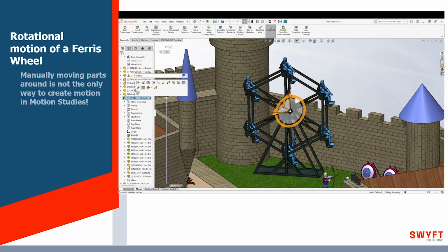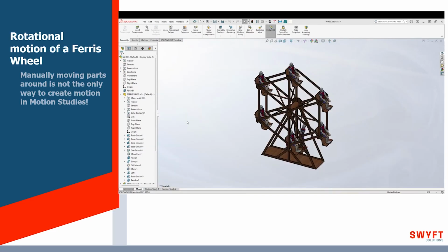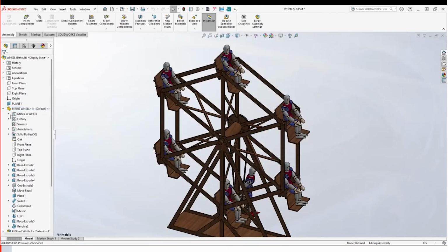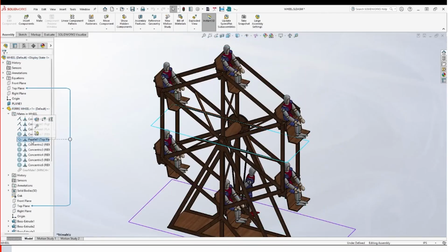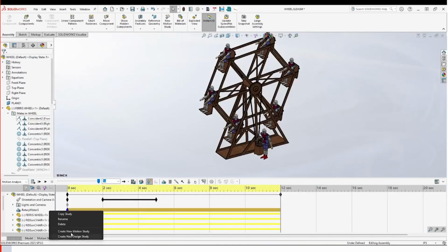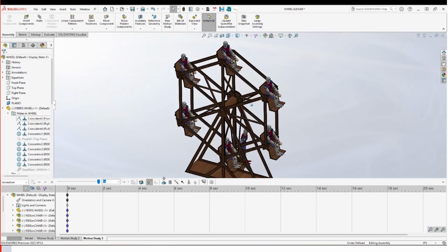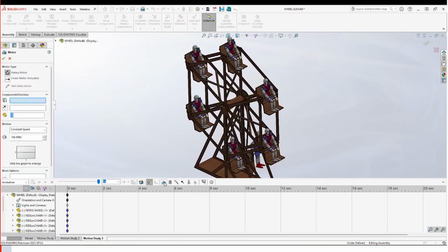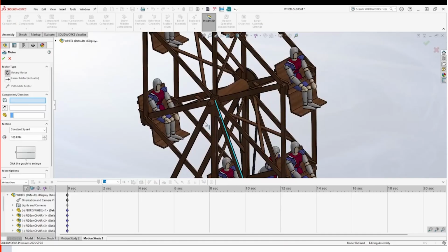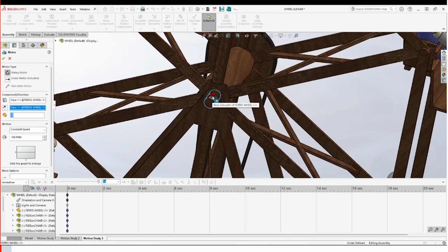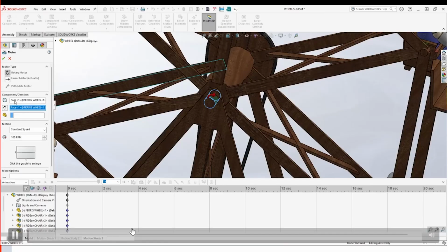And in this case, there's actually more things that I can add. I want to point them out when I pull this up, but right now it's locked. It's not going to do anything. Just like making a sub-assembly flexible that's fully defined isn't going to do anything. So right off the bat, I just suppress that mate so that when I go in my motion study, it'll run as expected. And just like your drawings down here, right click, you can make another tab for another motion analysis. And I don't know if you saw that. I didn't see it.